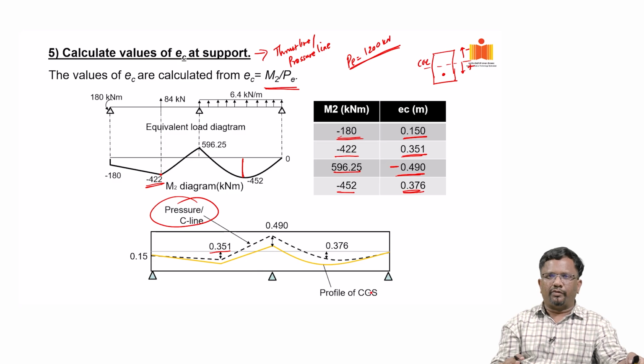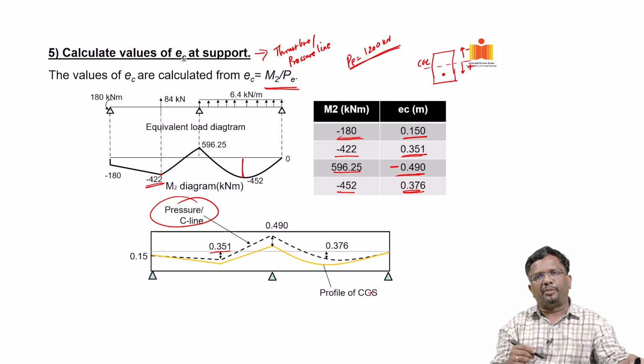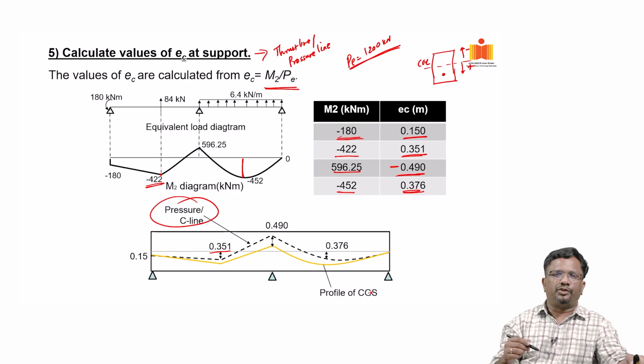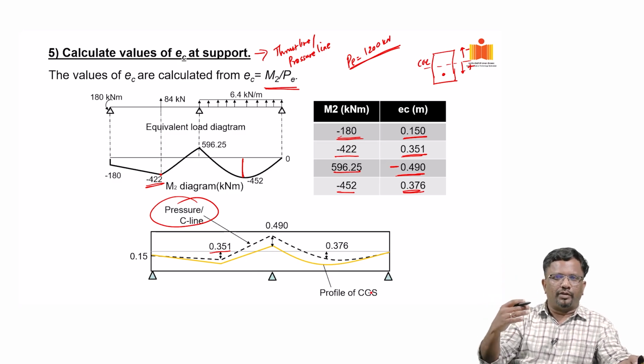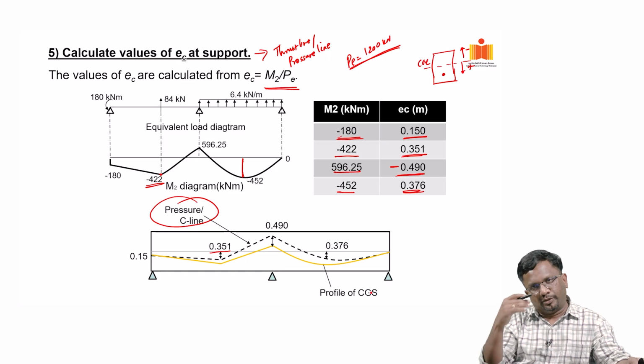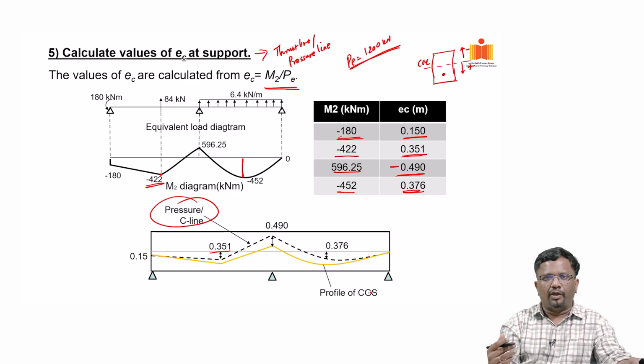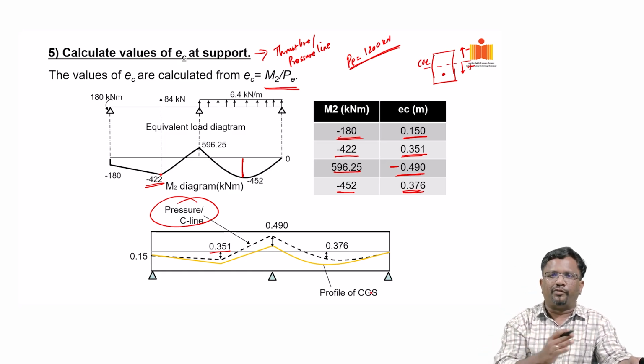So, we have to be very, very careful. For example, the positive benefits on the span locations will be reduced because of the secondary moment, but most of the time the negative moment demand when you design for it will come down. So, in one way secondary moment is beneficial, but at the same time you cannot say that for all locations.